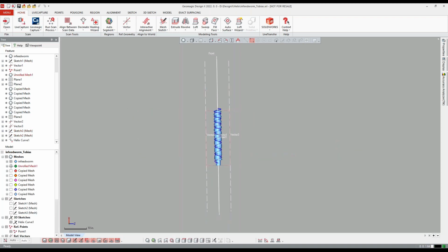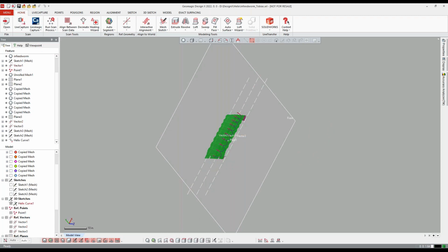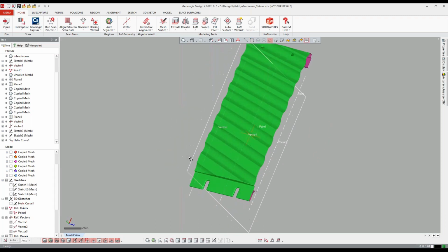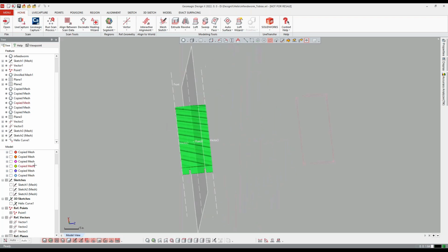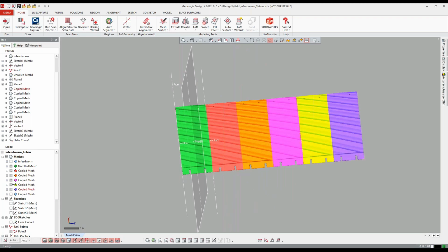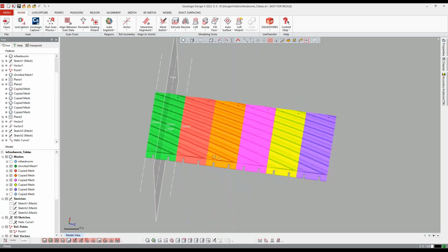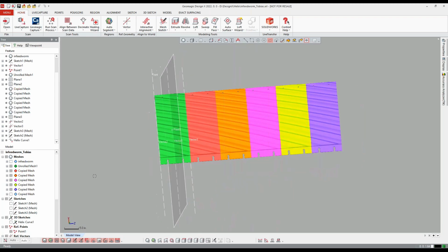Okay, what we do is we can actually unroll the mesh. This is a very cool thing Design X does. So I'm going to turn off this helix here. I can actually come in and flatten that. And then if you guys want to see where we're going here, what I'll do is we can copy. We can paste them all next to each other.